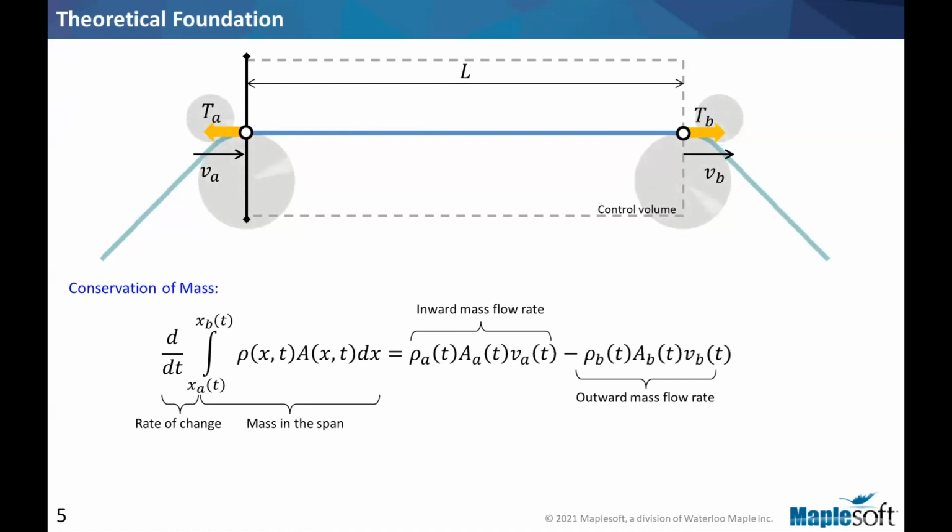But we are going to immediately make some simplifying assumptions that take care of some of these details. We're going to assume that over the span, things are constant. So strain in the material remains constant, and velocity remains constant. There is a change of velocity as the material enters the control volume, but inside the control volume, tension is constant. So TB, epsilon B, or strain, is the same.